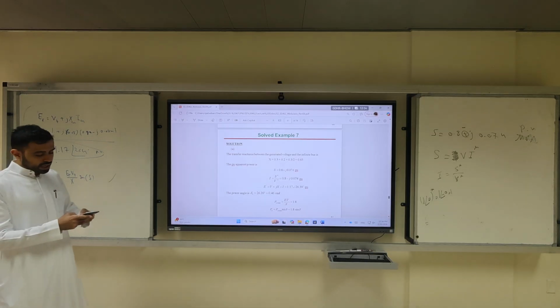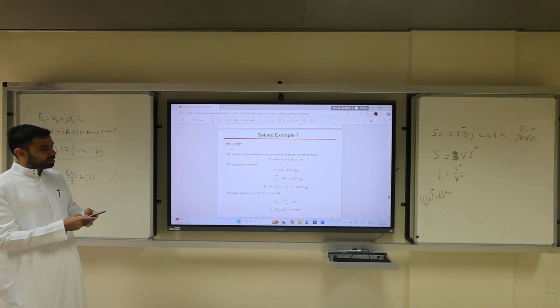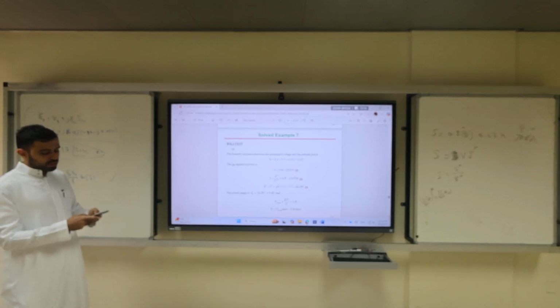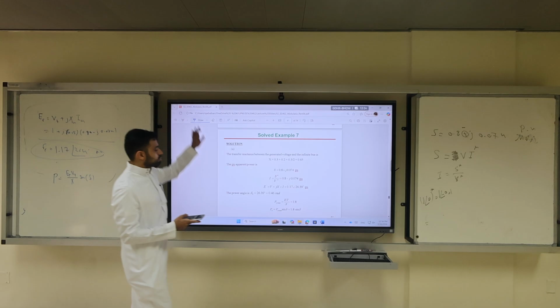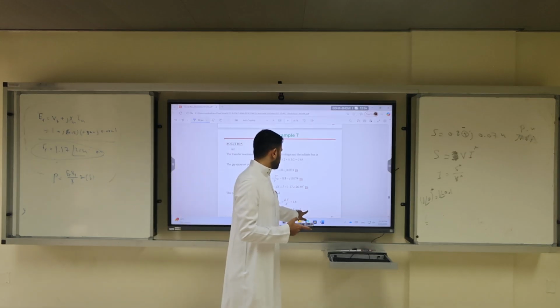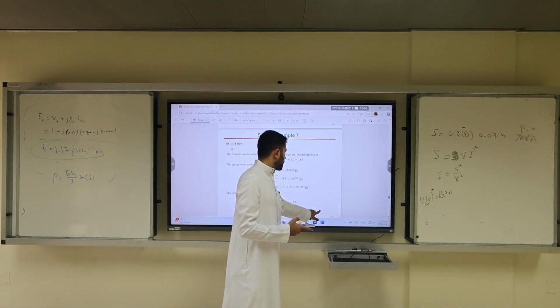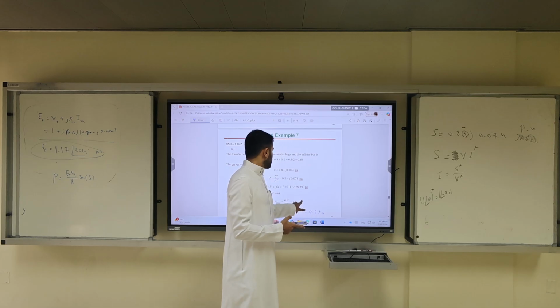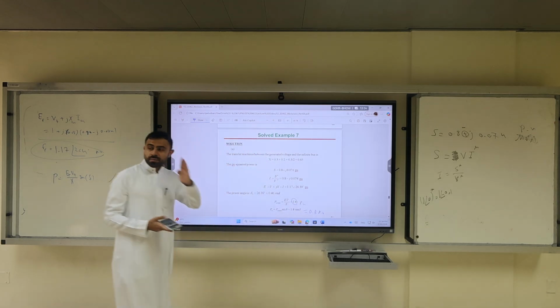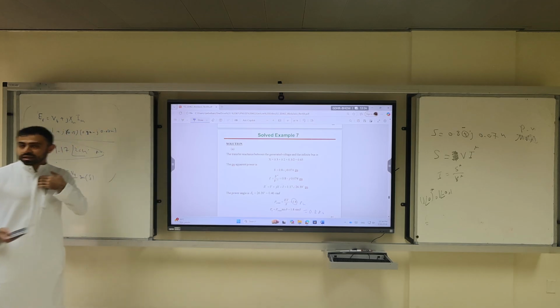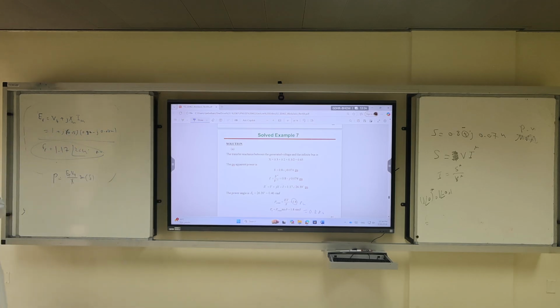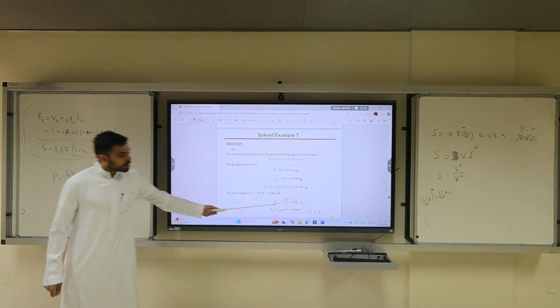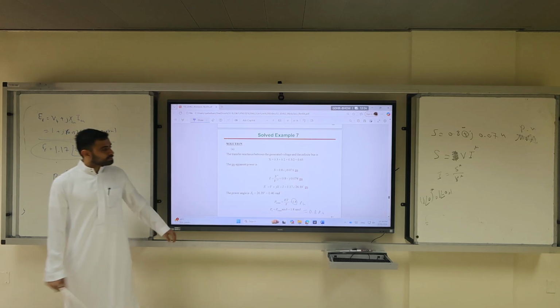It's 1.8 times sine 26.39, which is 0.8. What's the unit of 0.8? Per unit. So you can deliver 80% maximum, 1.8 per unit, and for this delta, you have 0.8. Clear?